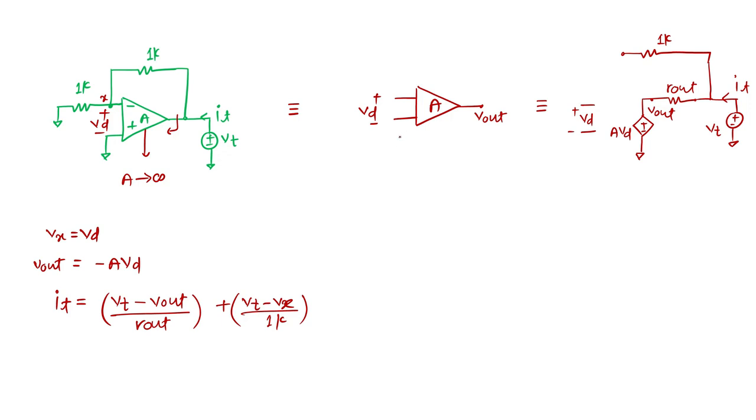Okay. So what is this current component? The current through this resistor is equal to the current through this resistor because there is no current going inside this amplifier. So another expression that we can consider is the current (VT minus Vx) by 1K is exactly equal to Vx by 1K. Just by network analysis, we can see Vt equals 2Vx, or Vx equals 0.5 Vt.